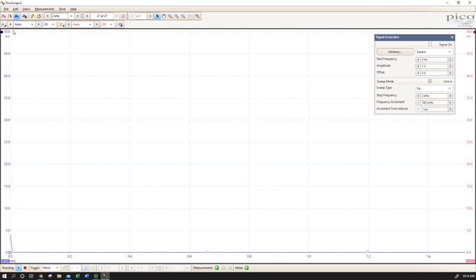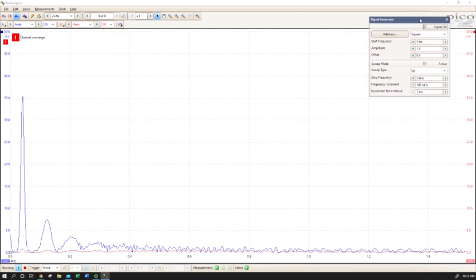And I'm leaving my voltage collection signals on auto because I don't quite know how they are. Eventually, if I wanted to show a very pretty plot of resonance, I might want to collect for a while and then put them on a hold over a Y scale that showed what I wanted. But I'm just basically looking to see where I will see a trough on my full circuit voltage and a peak on my resistor voltage. So I'm running. And now I'm going to go ahead and start sweeping my signal.